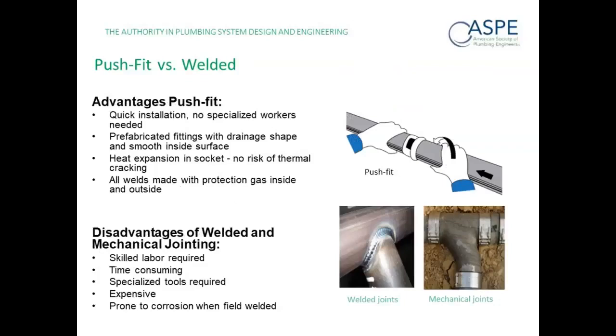Talking a little bit about the jointing methodology, push fit versus welded. It's a quick install. You can get in and out of these facilities very, very fast and keep your project moving. You can handle the heat expansion in the socket, so there's not a risk of thermal cracking due to the hot and cold that Scott had talked about earlier with the thermal expansion and contraction.